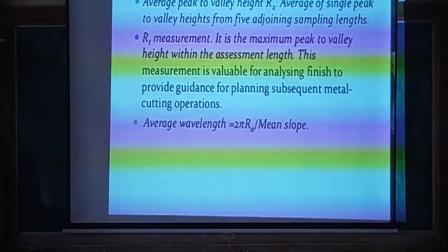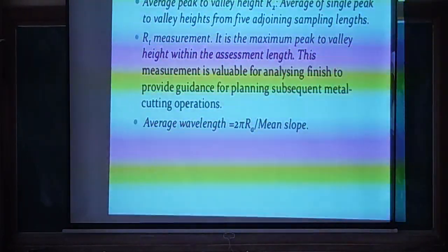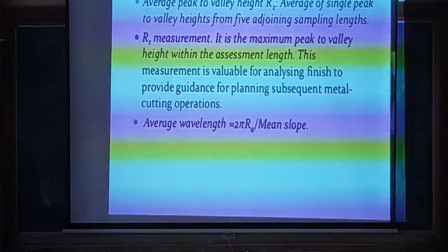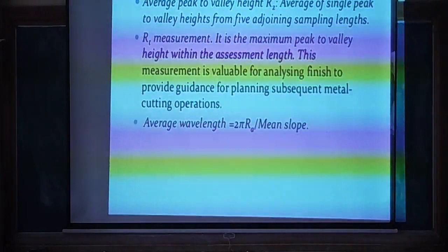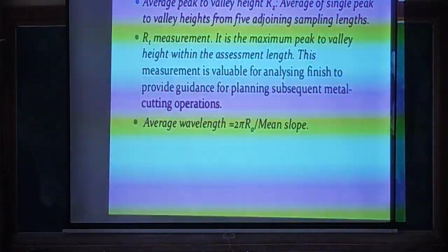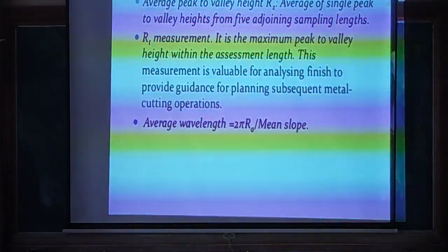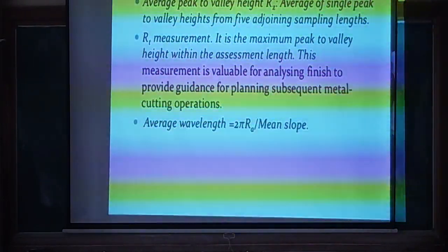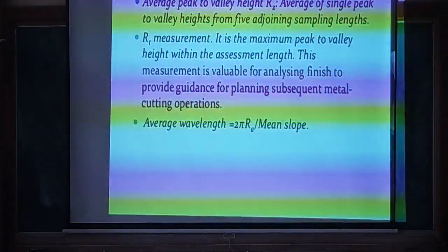Okay, this measurement is valuable for analyzing finish to provide guidance for planning subsequent metal cutting operations. The maximum peak and valley height within the assessment length is very important for providing guidance on how you are going to set that particular parameter in the cutting operation.